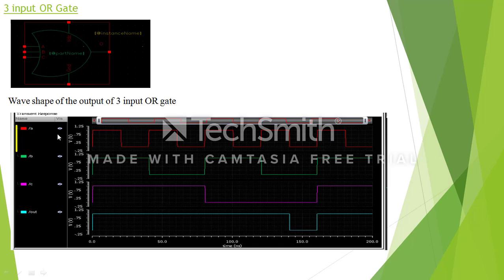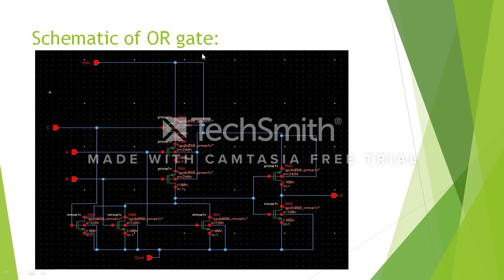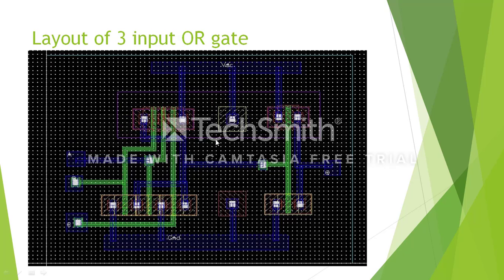3 input OR gate, the wave shape of the 3 input OR gate, and the schematic of the OR gate. Here one thing I want to tell is that for the OR gate circuit, the PMOS are connected in series and the NMOS are connected in parallel, which is shown here.